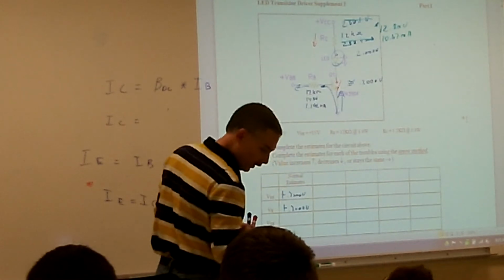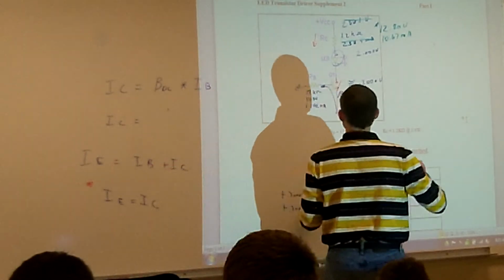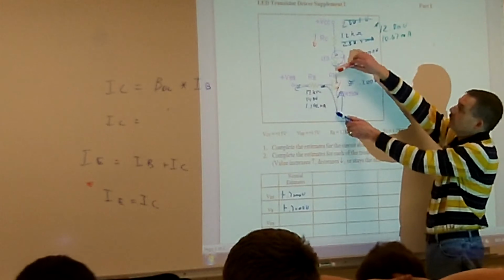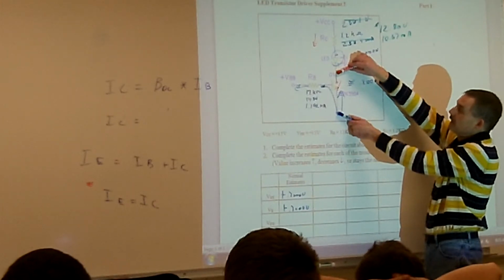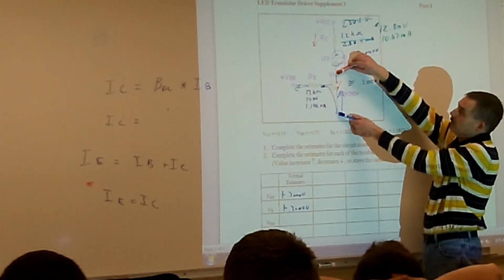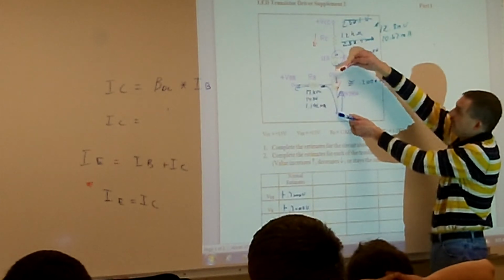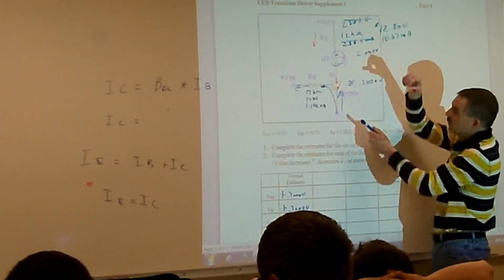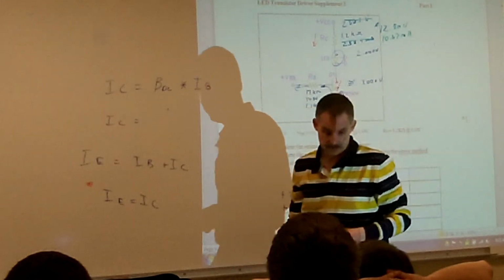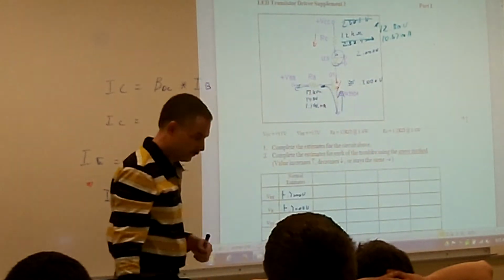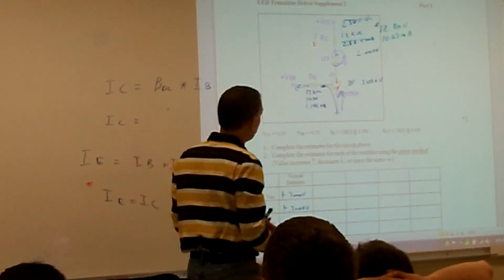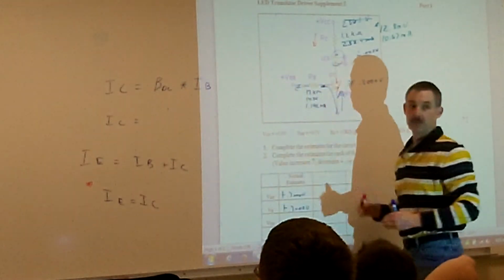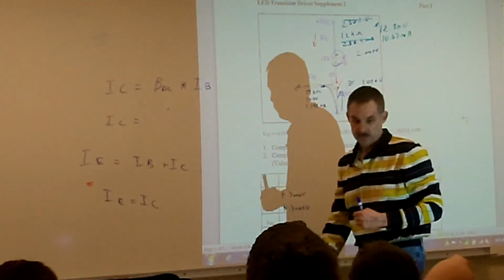Then the voltage from the collector. Basically, you've got your red lead on your collector, black lead on your reference point or your emitter. Come back down, you're going to have a positive 0.2 volts. Wouldn't you include the 0.7 volts as well? Nope, that's a separate circuit. Those are 2 separate circuits.